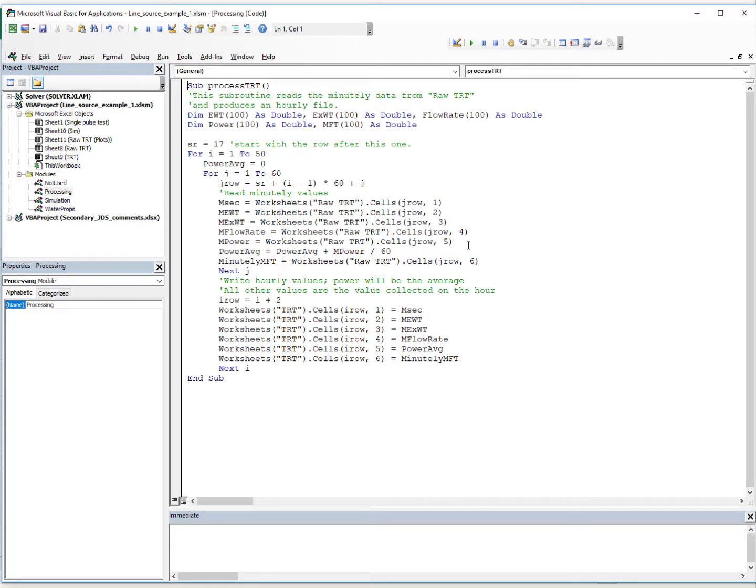As an aside, I realized that one thing I did that wasn't exactly consistent is for Q, I took the average for the hour, which is fine, but possibly when I calculated the delta T, I should have used the Q for that time rather than the average for the hour. It would make very little difference, I don't think, since we had a fairly even power distribution. But I tried to do everything else related to the borehole, where we assumed quasi-steady, with the instantaneous value at that point.